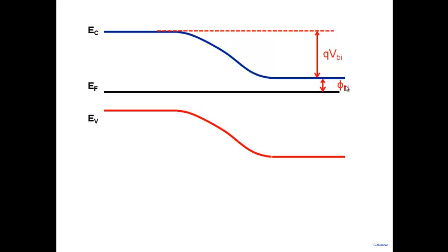So depending on the doping, I know phi n, the separation between EC and EF. Similarly, depending on the doping here, I know phi p, the difference between EF and EV. So I know these values. All right, so the way we start off, again, just to remind you, we start off from EF. We go around a sort of loop and come back at EF, right? So that's what we do.